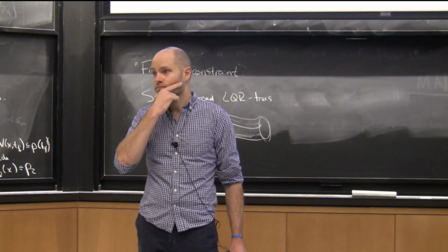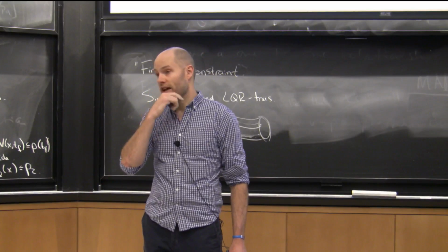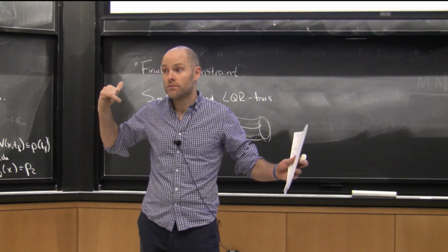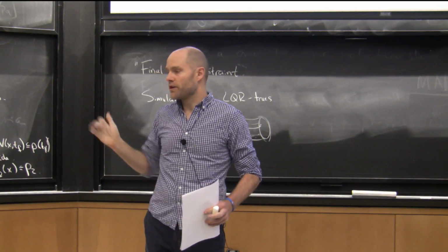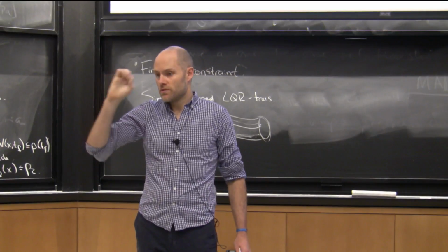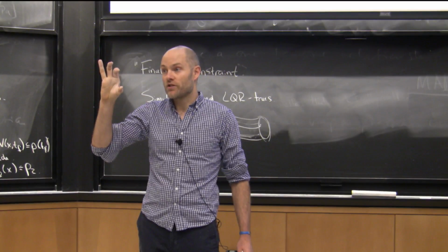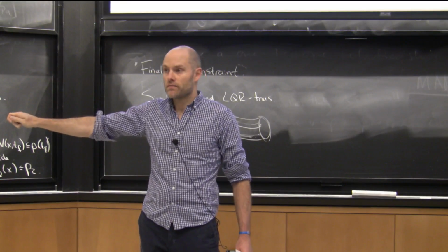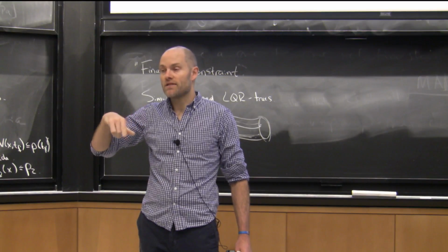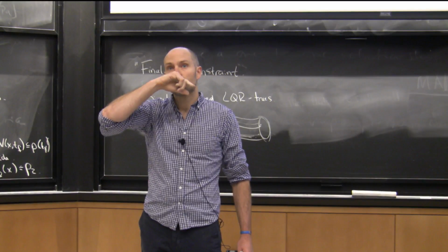Do you have a question? I just want to clarify, so this is all happening in real time? This is offline. Okay. The goal would be to come up with a feedback controller, which is represented as a tree, much like the RRT tried to pre-compute a tree from the goal, and then at runtime, what you do is you get whatever your current state is, you find one of the funnels that you're currently covered by, and you start executing. So this is an offline design process, and the next slides are about how you make it online.